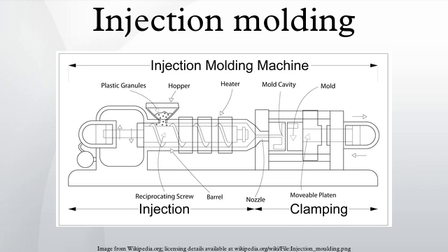The screw delivers the raw material forward, mixes and homogenizes the thermal and viscous distributions of the polymer, and reduces the required heating time by mechanically shearing the material and adding a significant amount of frictional heating to the polymer. The material feeds forward through a check valve and collects at the front of the screw into a volume known as a shot. A shot is the volume of material that is used to fill the mold cavity, compensate for shrinkage, and provide a cushion to transfer pressure from the screw to the mold cavity. When enough material has gathered, the material is forced at high pressure and velocity into the part-forming cavity.